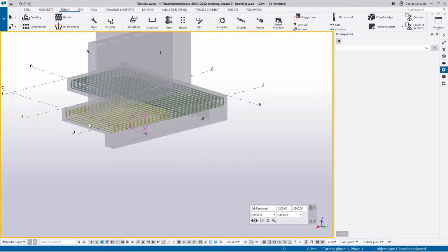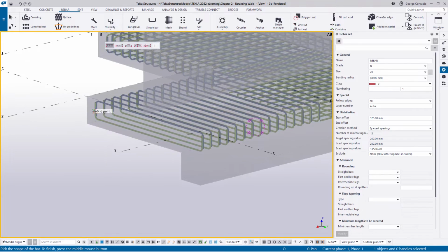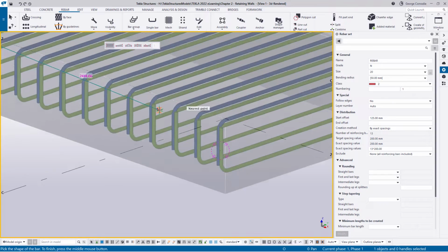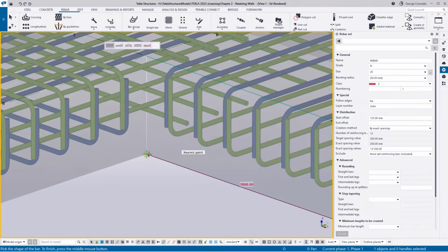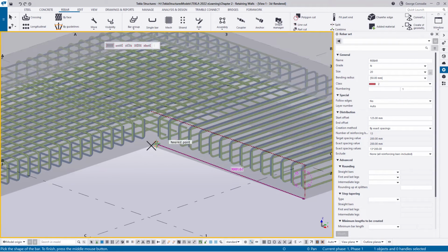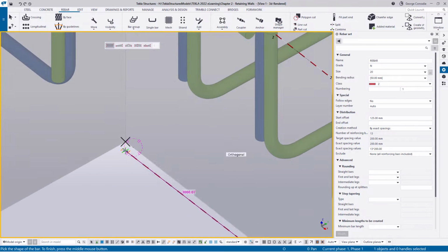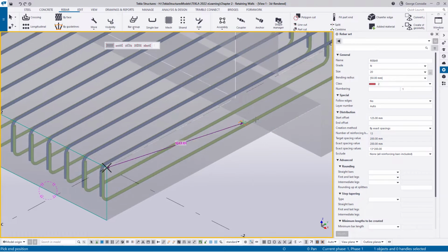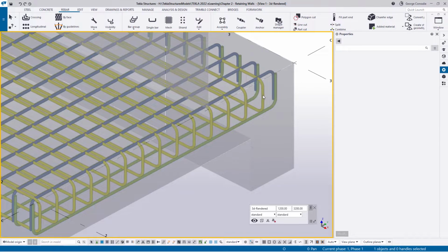So what we can do here is on this side, again, we can go more point input. And what I'll do here is I will start over into the back corner top, over to this end, to the bottom, and then back to this. Oops, to this. Didn't snap. To this. Sometimes it's quite challenging to snap. There we go. Snap, and then middle mouse to accept that, and this will then go from this end to that end, and it will place the bars. Now you can already see there that we've got two in the same plane.